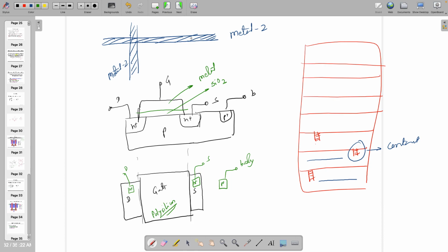If you do not want that, then you need, let's say I'm adding metal 3, means on the third floor, or maybe metal 4, metal 5, metal 6, and note that the highest metal is available at the output, visible at the top, and that is the place where we are connecting all the pins, right? So not from here, and here generally substrate is there, p substrate at the bottommost. That is how this whole chip is actually being made.